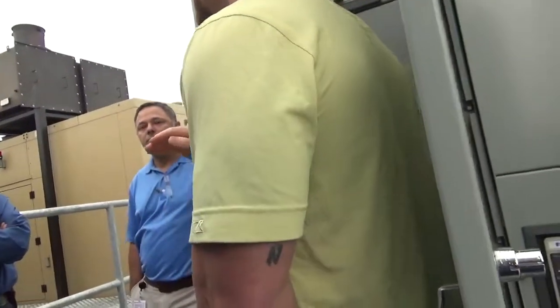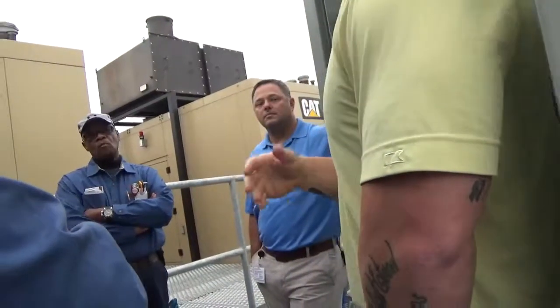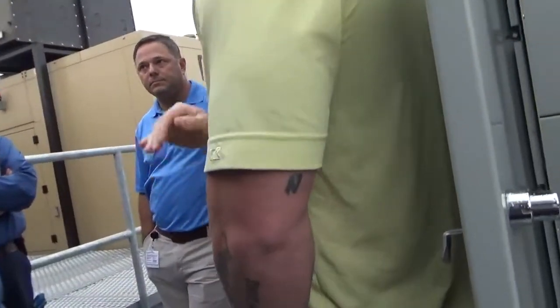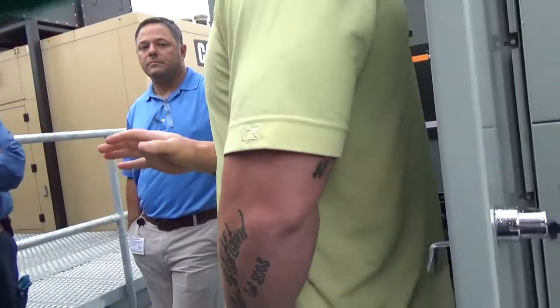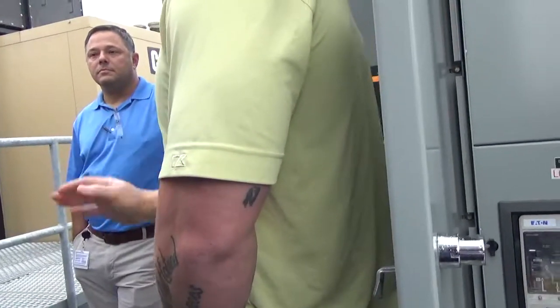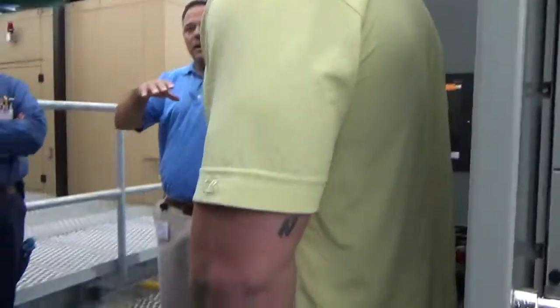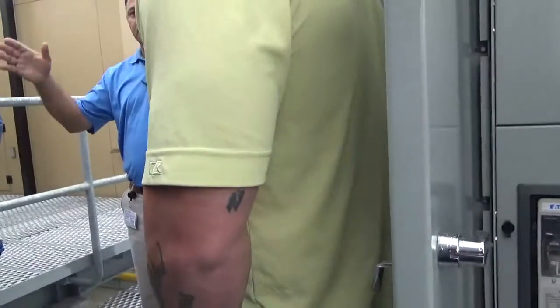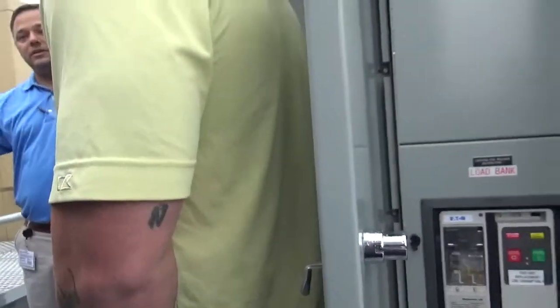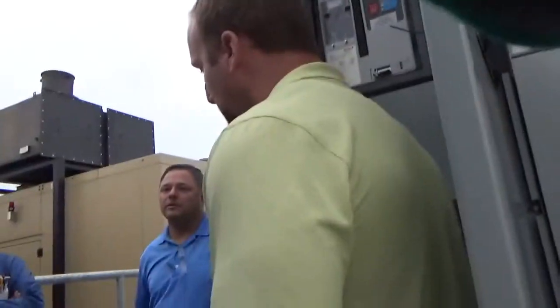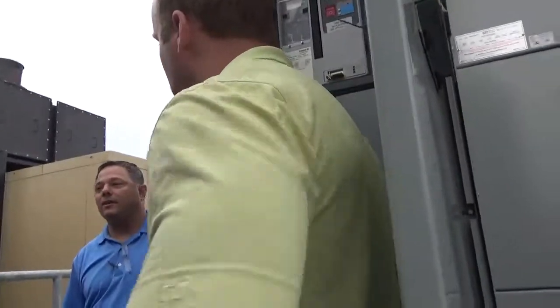And that'll be like equipment or certain loads. You're never going to drop life safety. Life safety will always stay on there. Life safety critical loads normally in a hospital will always stay on there until the gen burns to the ground. So you have 2 generators and you're running 80%, 20%. You drop a generator, it's going to drop off one of those blocks so you don't overload the one generator, right? Which we have a long way to go.